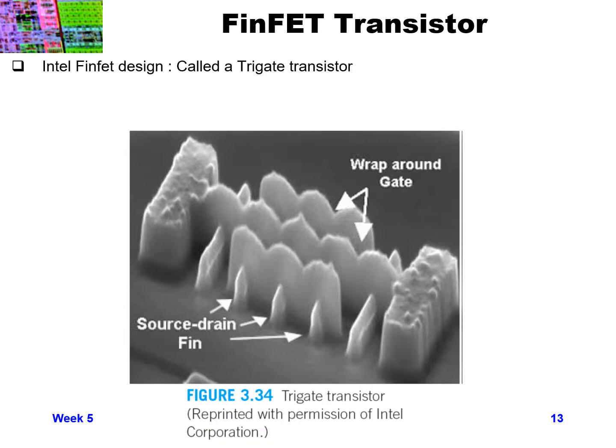So you don't just have a single electric field across the entire channel, but you get slightly different electric fields as it wraps around the fin of the transistor. And so they call it a tri-gate transistor. You can see these look much more fragile, much more complex than your traditional flat transistor.